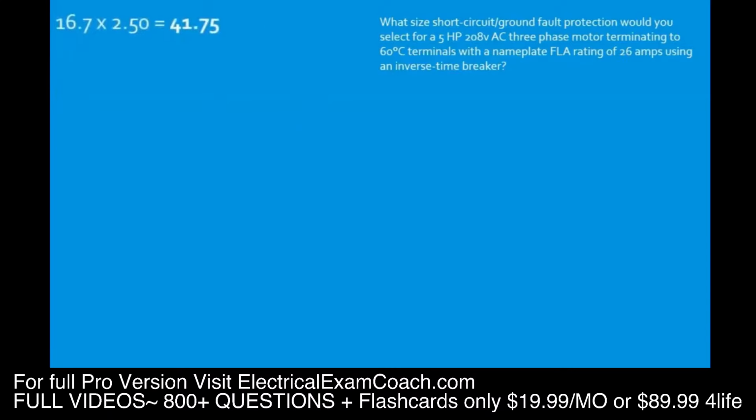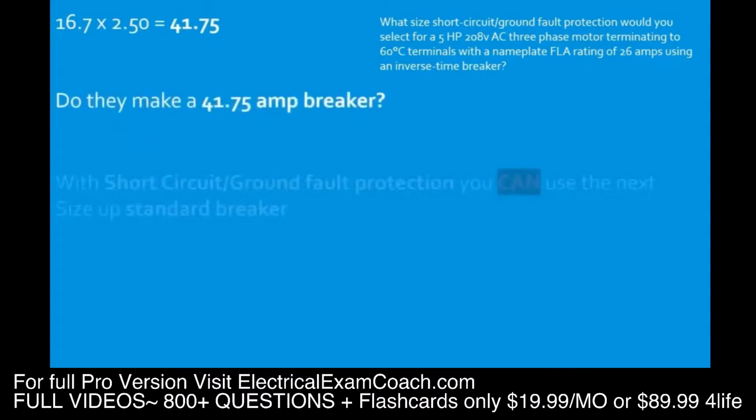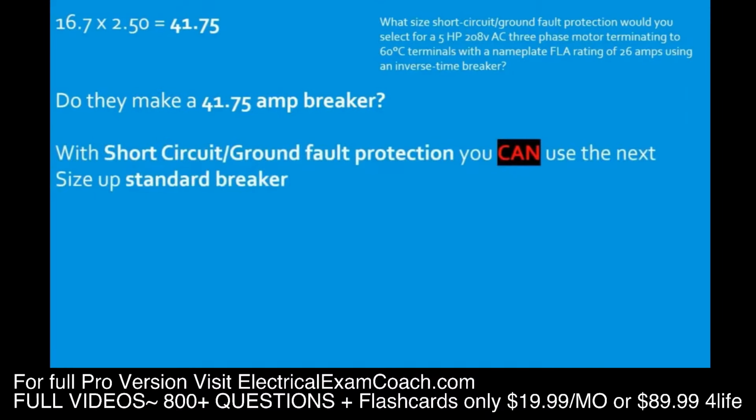All right, so we did our math. Now, do they make a 41.75 amp breaker? And the answer is no. I want you guys to know that with motor short circuit ground fault protection, you can use the next size up standard breaker. When we get to motor overload protection, you cannot. So with short circuit ground fault protection, you can use the next size up breaker. So we head to table 240.6(A) and we find a breaker that is the next size up from 41.75 amps. And in this case, it's going to be B.